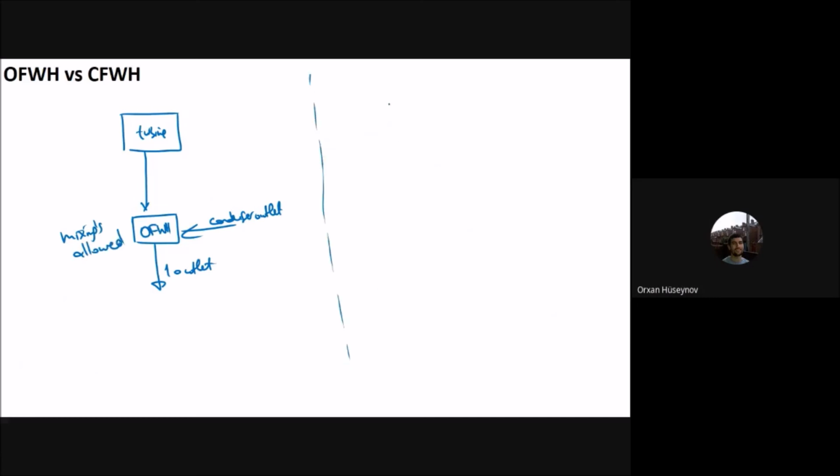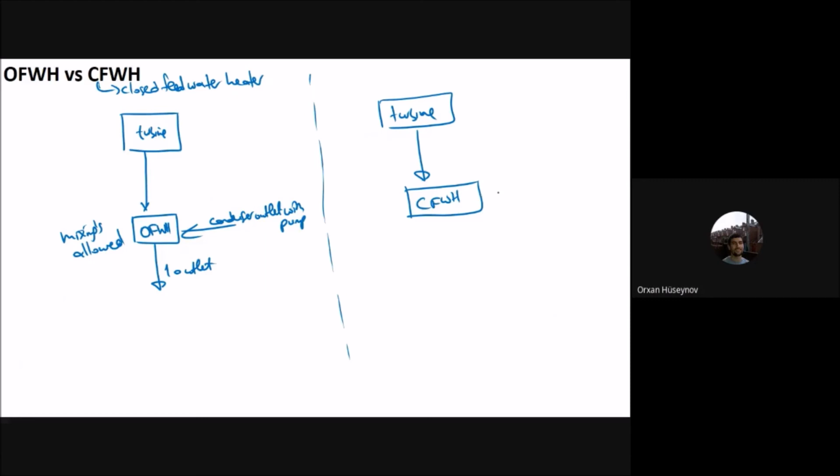What the opposite may happen is that you have the turbine, but here you will need some condenser pump. Here you will need some pump anyway, so you have that outlet with pump. So you have the turbine, and you have the closed feed water heater. This one is closed. For this closed feed water heater, again I will use the condenser outlet with pump, and I will use the turbine again. Everything is okay, but here you don't have the mixing process. So since you don't have the mixing process, it goes in that direction and in that direction. Here you don't have any mixing.